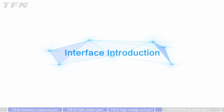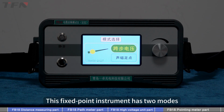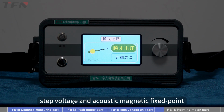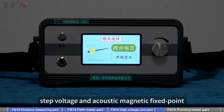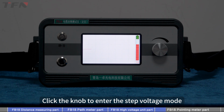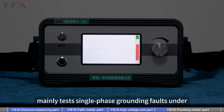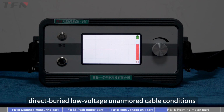The left side is the earphone port, and the right side is the data port and the charging port. Interface introduction. After the instrument is turned on, enter the mode selection interface. This fixed point instrument has 2 modes, step voltage and acoustic magnetic fixed point. Click the knob to enter the step voltage mode. High voltage step voltage mode mainly tests single phase grounding faults under direct buried low voltage armored cable conditions.